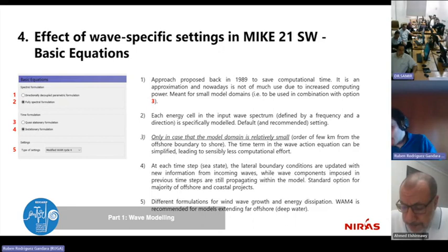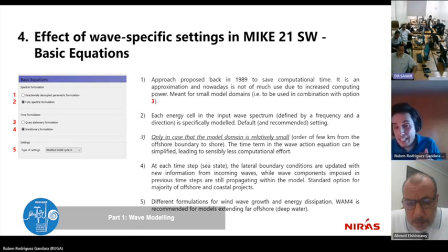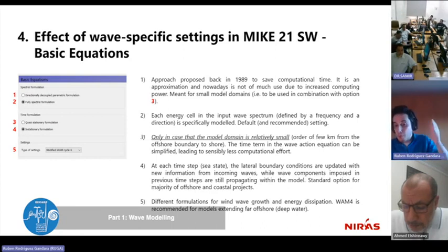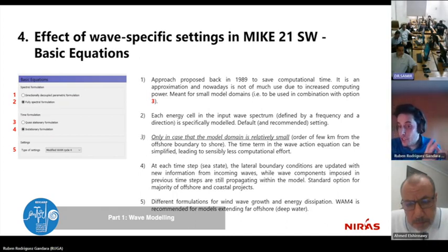The following time step in your forcing is 1 hour after. But your domain is so small that the time it took for the waves to travel from the boundary to the coast is smaller than the time resolution of what you're imposing at the boundary. So basically that transformation of waves from the boundary to the coastline is instantaneous.